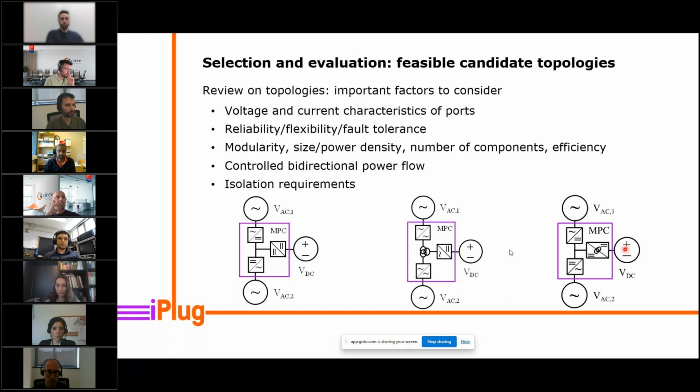So from all this, a little bit of a description: this is a typical back-to-back where half bridge sub-modules are used, where you will have a high DC link and you would have to realize a low DC voltage with a DC-DC stage, non-isolated. And this is a common topology we were also investigating in the project, where the isolation stage or the interconnection between the ports is provided by a high frequency transformer, or as we call it DC-DC stage, which the SSTAR partners will present later on.